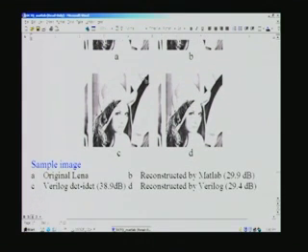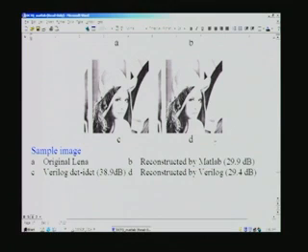and this is Verilog created DCT, IDCT, and you see a very high decibel here for this. It is as good as the original. So a good quality picture is supposed to be 30 dB and above, and a bad quality is 25 dB and below, and indistinguishable quality you will get if it is 35 dB. That is the thumb rule for finding out how the picture is, apart from the visual findings. And this is for the reconstructed by Verilog.